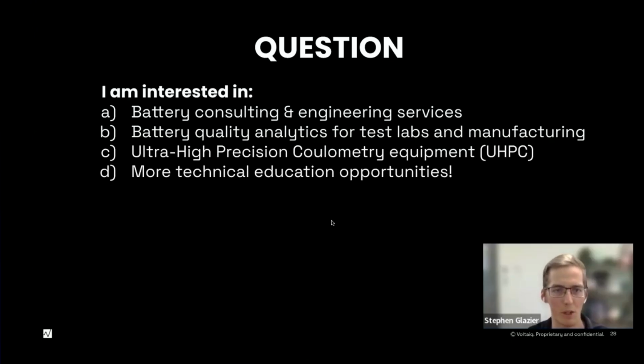I think it's like thinking about equivalent circuit analysis in EIS. You can add 1 million circuit components until you get a nice perfect fit, but does it really mean anything? And one of the quotes that I'll always remember from Dr. Jeff Dahn was, with equivalent circuit modeling, you could fit an elephant. So he's just saying you could just add as much stuff until you could fit any shape. So it is, like you said, you have to be very careful in interpreting what the peaks you're putting in there really mean.